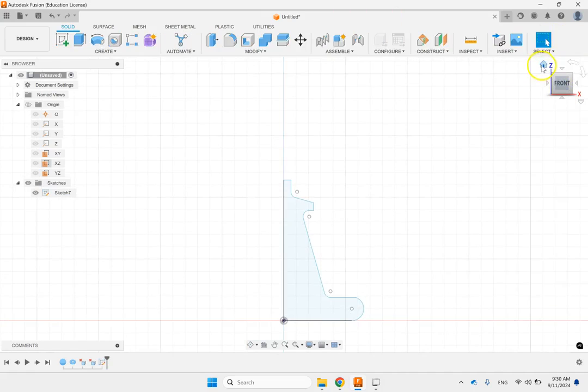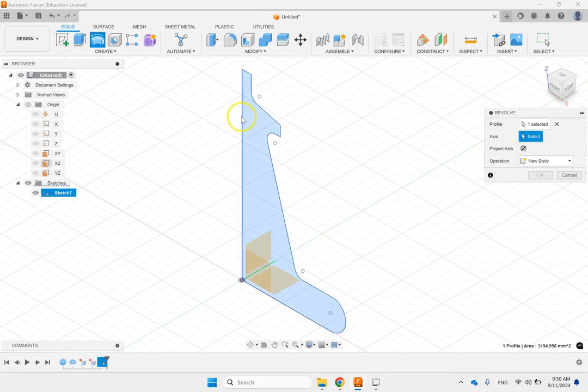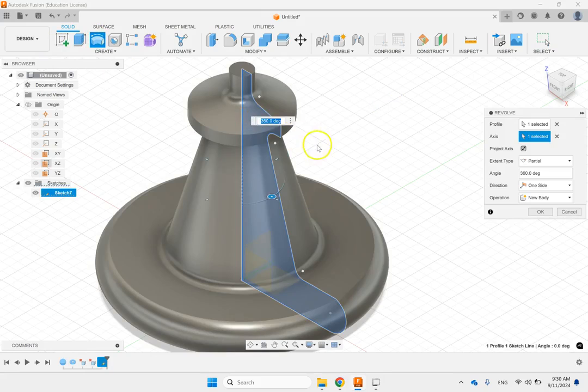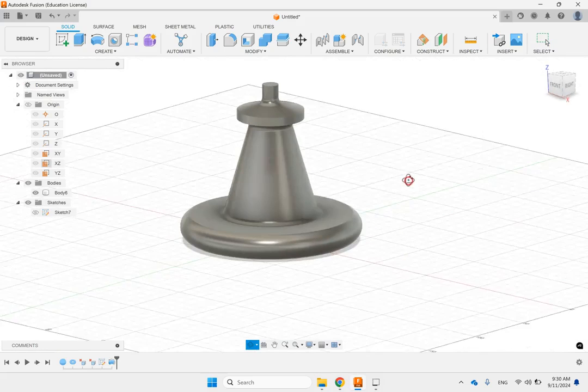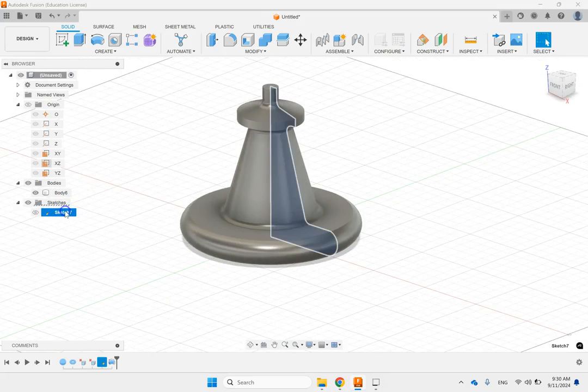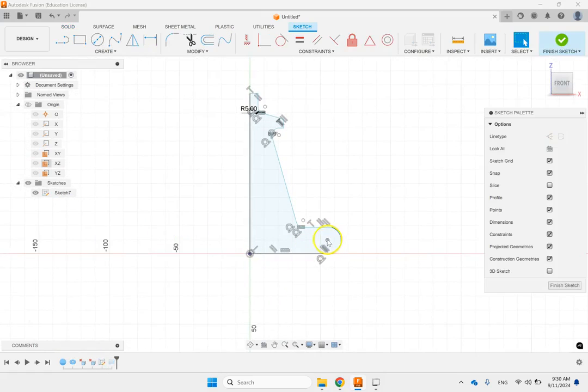And of course, now you have an axis, which is this line. So I click on the revolve command and I pick this line for the axis. And let's say this is a pawn. Of course, no big design involved here. And then you can go full 360, or you can go partial, or you can go one way or the other way, right? So let's say here is a very bad design pawn, but basically this is all you need to do.